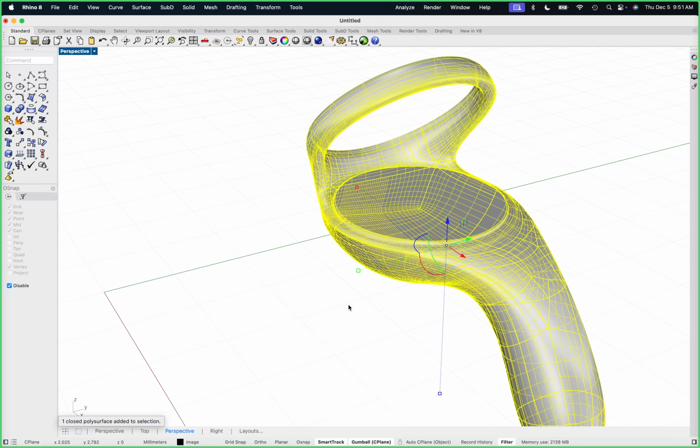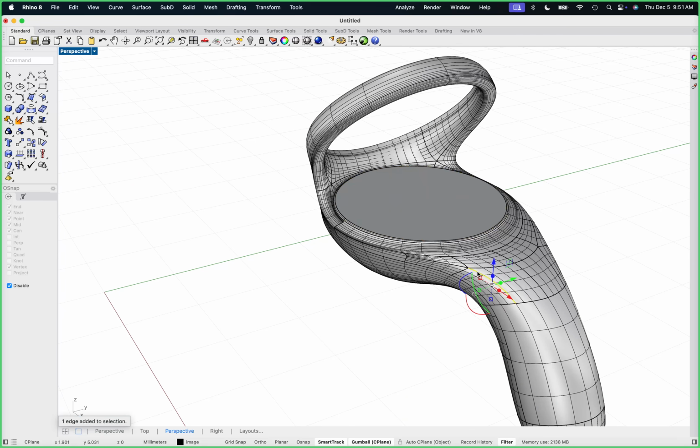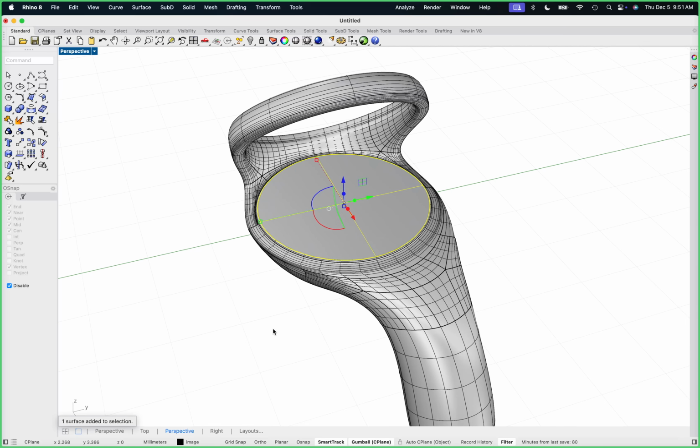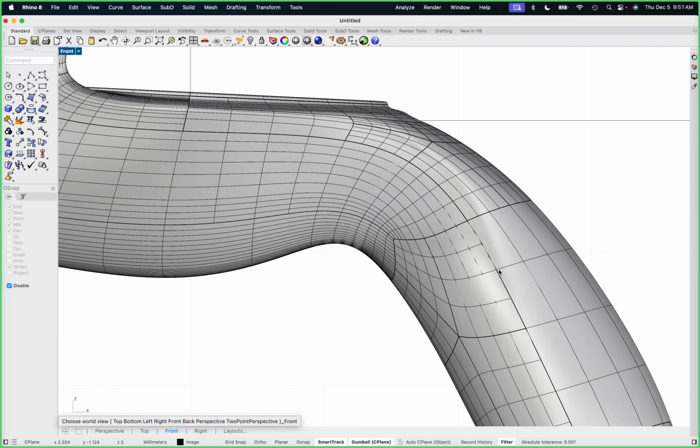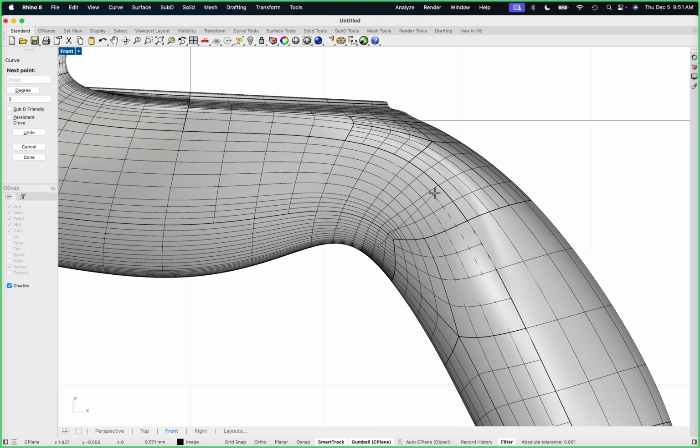And you can see that now we have a NURBS object booleaned into another NURBS object, but the NURBS object was generated from the SubD. And this gives us a really clean platform to kind of work from. So let's put the button on next, because that's another fun part. So let's take this, and we're just going to draw a curve. And I'm going to start, and I'm going to just kind of randomly figure out where this button is going to go. And this will be something that we would have to do some testing on.